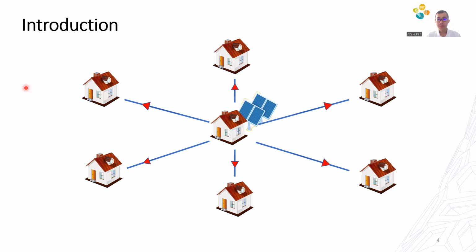And considering the impedance on the electrical lines, which means shorter paths, less power losses, we can say that in this scenario, placing the PV here in the middle is a better solution than putting it here. And it tells us placement of DGs matters.